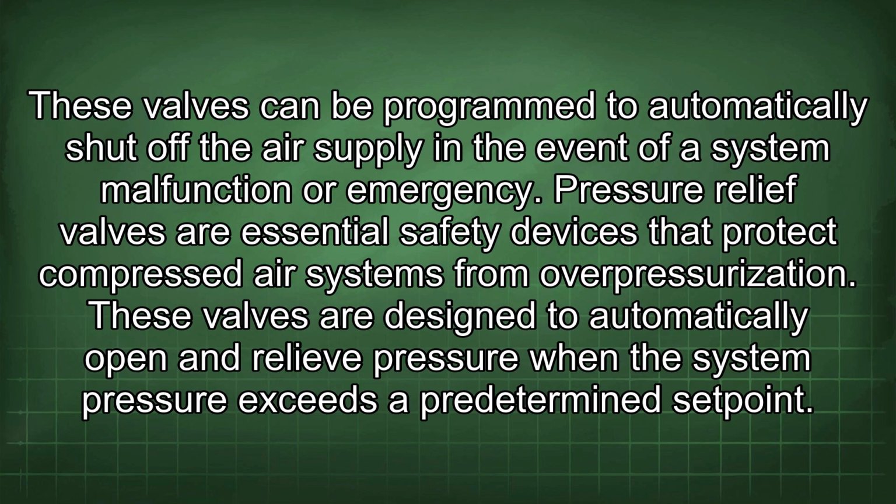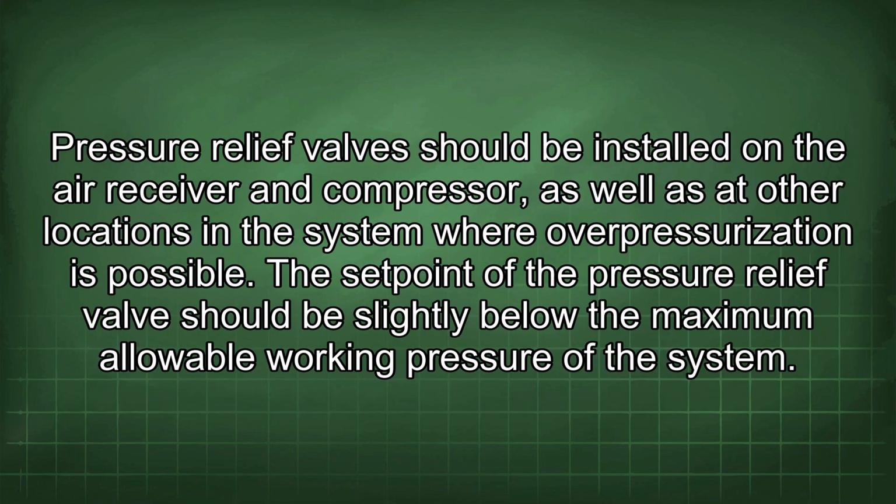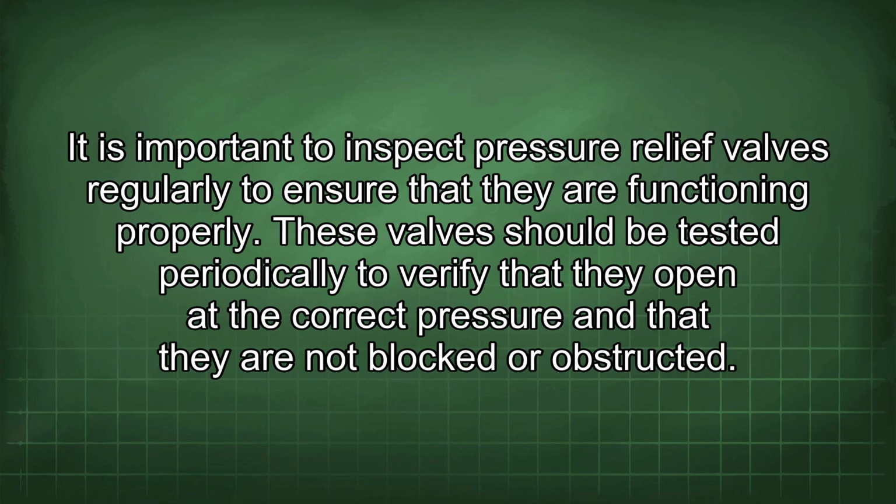These valves are designed to automatically open and relieve pressure when the system pressure exceeds a predetermined set point. Pressure relief valves should be installed in the air receiver and compressor, as well as at other locations in the system where overpressurization is possible. The set point of the pressure relief valve should be slightly below the maximum allowable working pressure of the system. It is important to inspect pressure relief valves regularly to ensure that they are functioning properly.